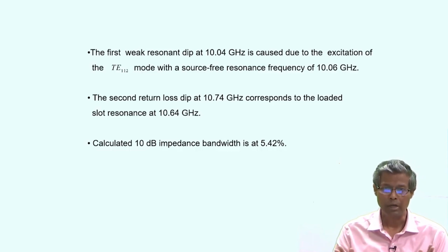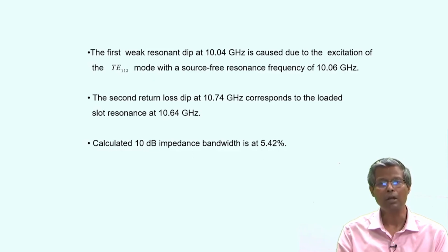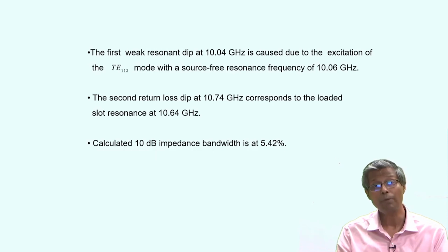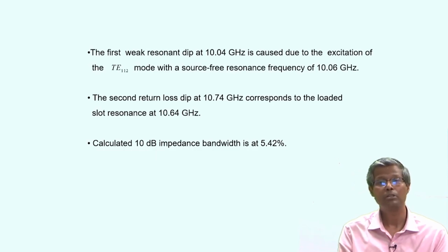The computation time drastically reduces, and for large antenna structures the analysis is much faster using the Green's function technique based on the modes compared to the simulation tools.